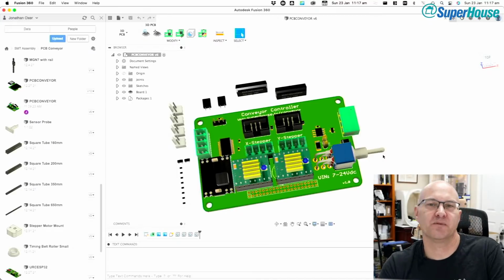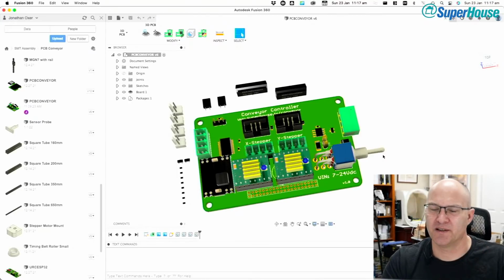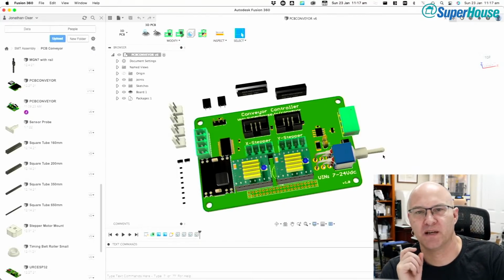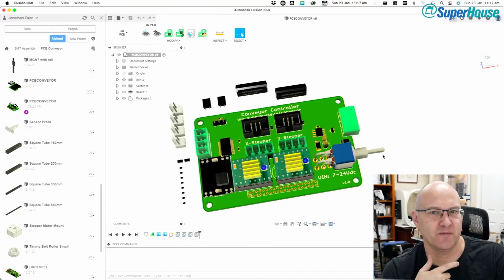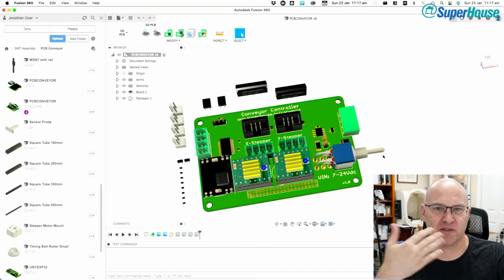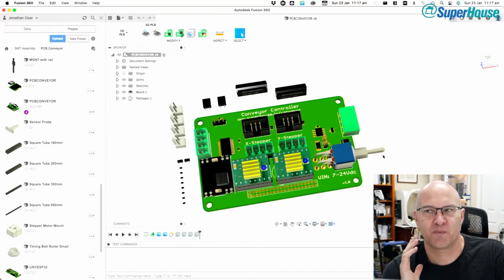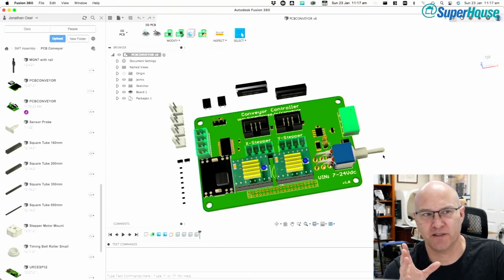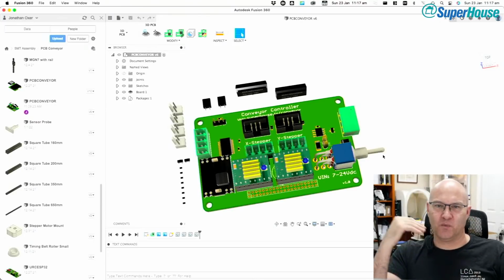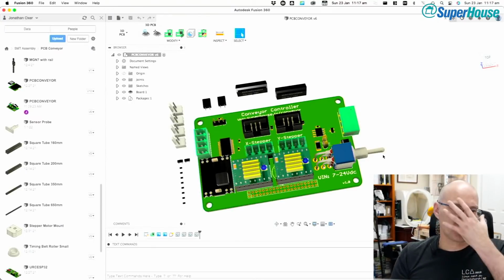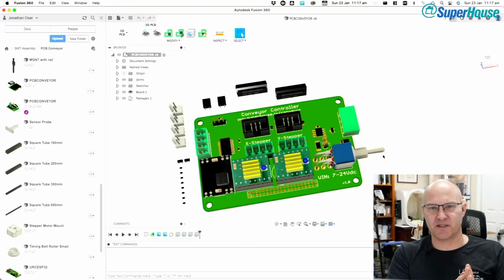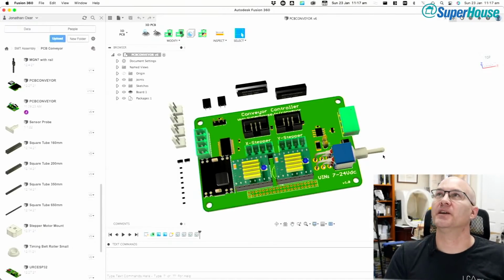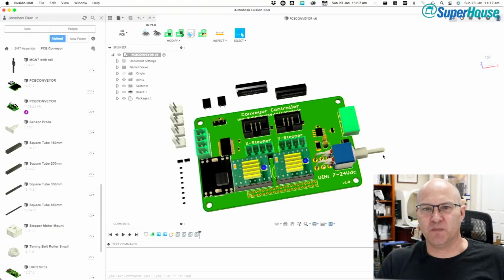So CAN, all right. What I was thinking is these have Wi-Fi. So right now, that prototype that I've been showing you, I can publish G-code commands to MQTT, and it responds. I can tell it to home, I can tell it to go to a position, etc. But that's using Wi-Fi, and I do not want to rely on Wi-Fi in the production environment. I want wired communications. The first thing I thought of, as Austin suggested, was PoE, and Ethernet with PoE, which solves the power problem as well. One cable, you plug it in, and you're good to go.